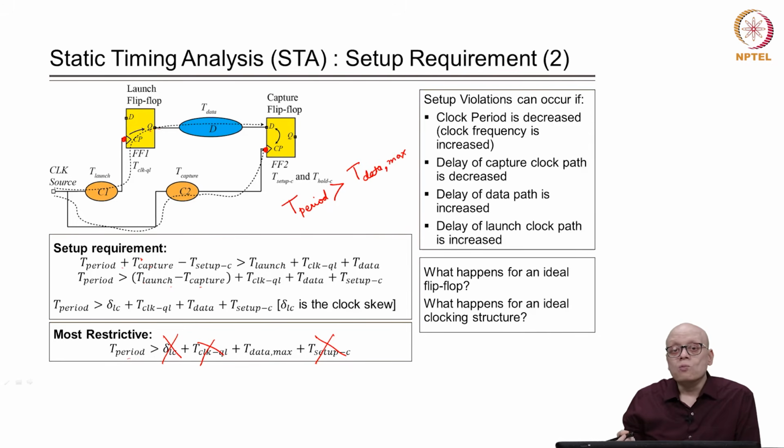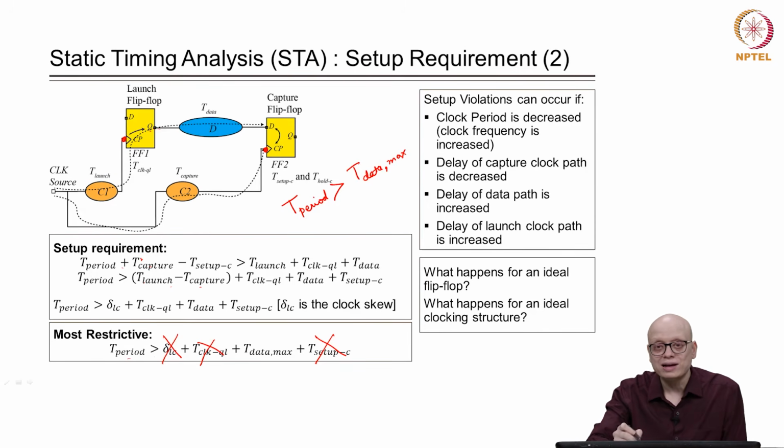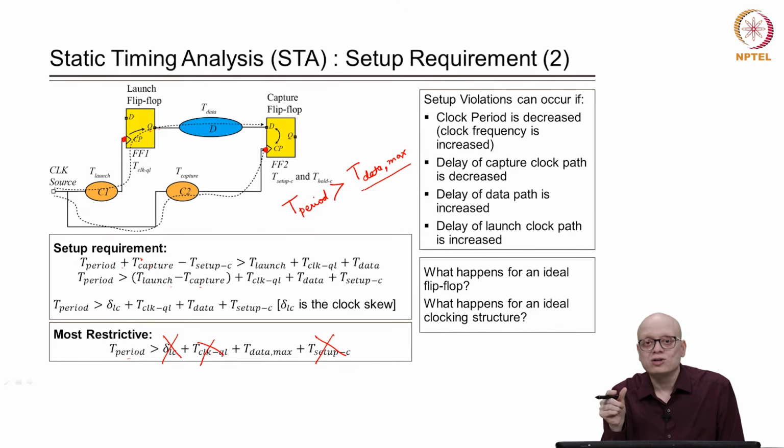Now, what does this constraint signify? This constraint basically signifies that there is no zero clocking in our circuit, right. We discussed earlier that zero clocking can happen only when the delay between the two flip flops is more than one clock cycle.